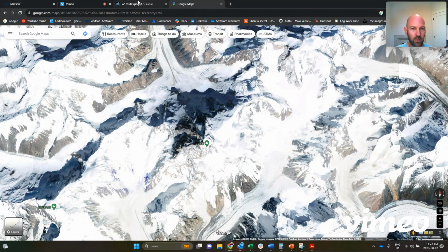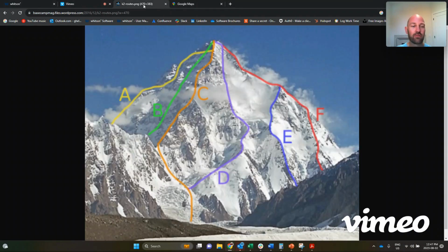So when mountaineers are planning their route to the top, there's different ways they can get there, different pros and cons, but ultimately their goal is to get to the top. The same is true when it comes to liquid loading in a gas well. There's different ways to avoid liquid loading, with compression, changing the tubing size, but our goal is to increase our production, maximize it, and delay that liquid loading, all right? But there's different ways we can do it.